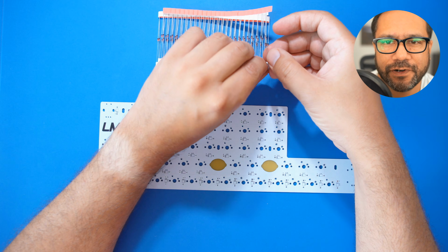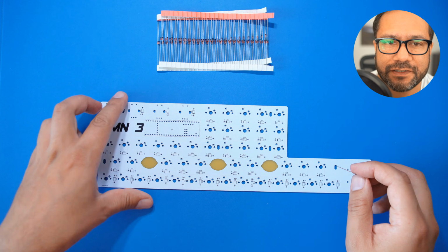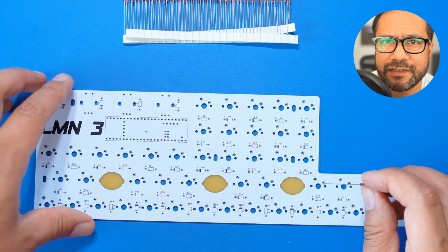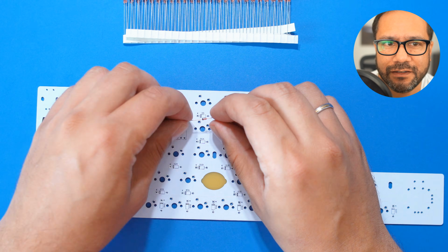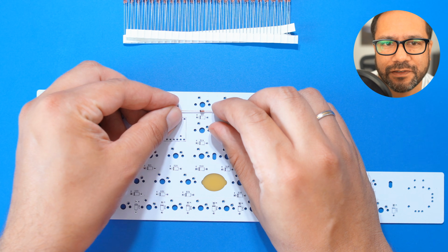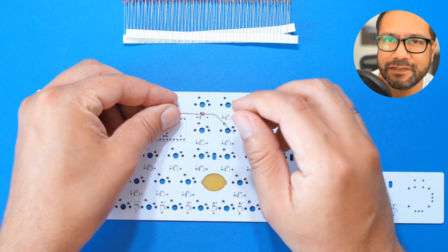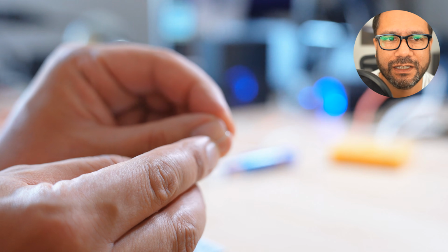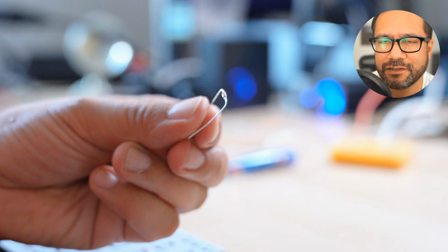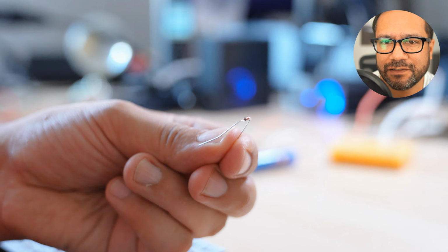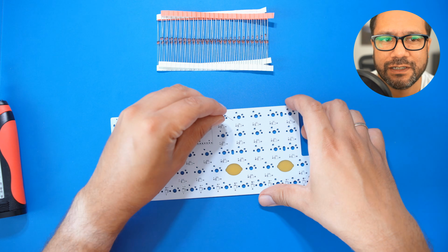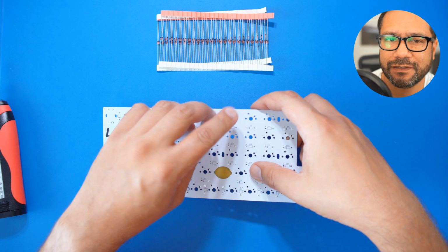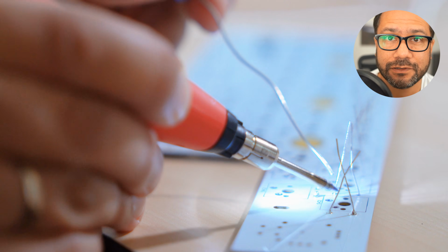Place the board in front of you so the smaller edge is facing right, and now take a look at the symbol on the PCB. There's a black line on the left side. You need to insert the diode so the black ring found on its body faces the same direction. It's a good idea to bend the diode's legs over your thumb, some millimeters away from its body, before placing it on the board so you don't damage it. Now pull the legs through the tiny holes, press the diode down onto the PCB firmly and solder it.